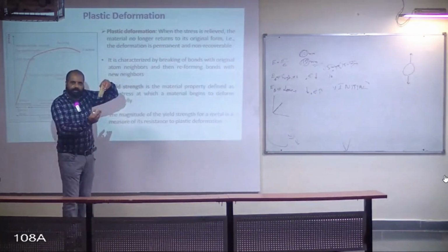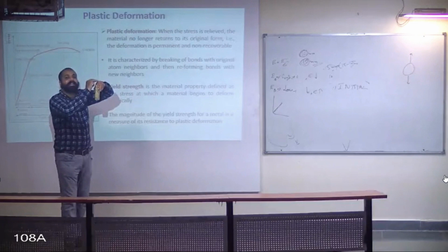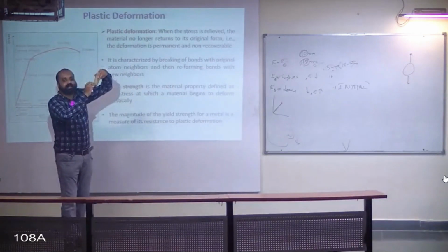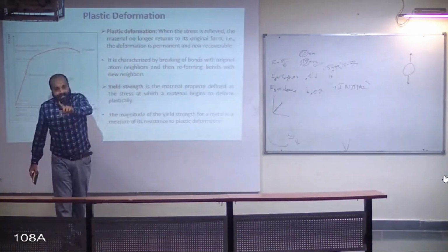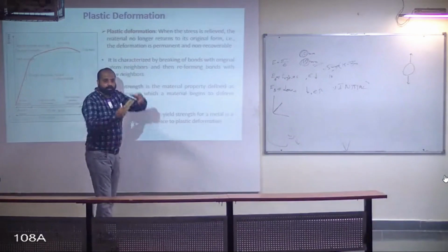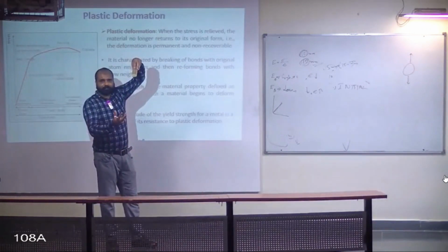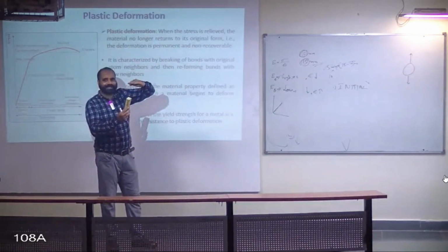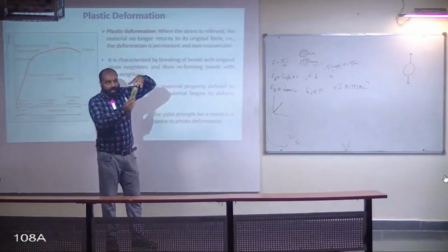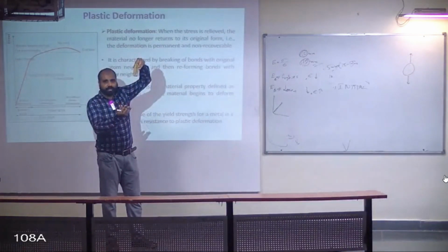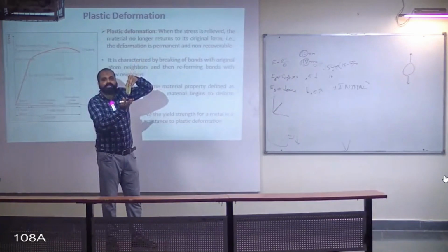Initially elastic deformation होगा, but after certain level of stress, if you exceed that level, the deformation will be plastic. Plastic deformation means when you release the stress, if you exceed certain limit of stress, and if you release that stress, the dimension will not come back to the original dimension.